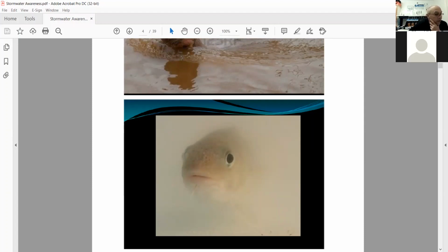So turbidity is a general term used to describe the cloudiness or dirtiness of water, like this around the fish. It gives a numeric value to determine how bad the water is. The turbidity of any given sample is determined by passing a light through a sample, measuring the reflected scattered light, and then using that to determine numbers of nephelometric turbidity units, or NTUs. Turbidity is a good measurement of a water body's health.